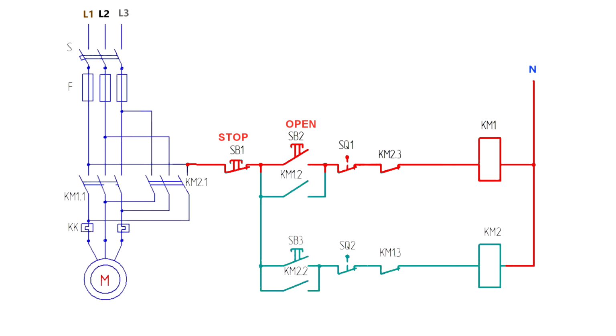But suddenly the engine stopped working, and the valve stopped. What happened? Why did this happen? But because the operator released the open button. Since the open button is non-latching, the electrical circuit is open, and the voltage in the control circuit is gone.